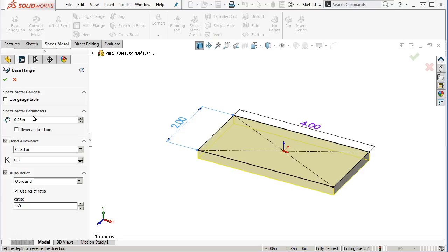So just like the weldments is going to produce a weldments placeholder, sheet metal is going to produce a sheet metal placeholder, and it's going to retain this information. Sheet metal parameters are 0.25, quarter inch. I want a 10 gauge aluminum, so let's call it 130. And be aware that when you go to the gauge tables for aluminum, steel, and stainless steel, there are minor variations in the gauge sizes. So verify. Check it and make sure that you know, within the tolerance zone, it's probably okay most of the time. But getting into finer, trying to hold the precision detail, 10 thousandths is going to affect your overall dimensions.